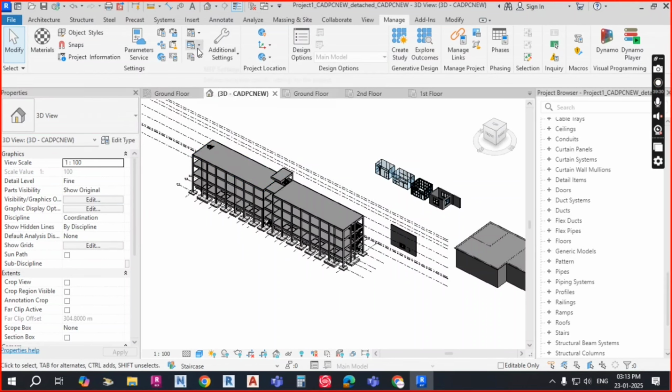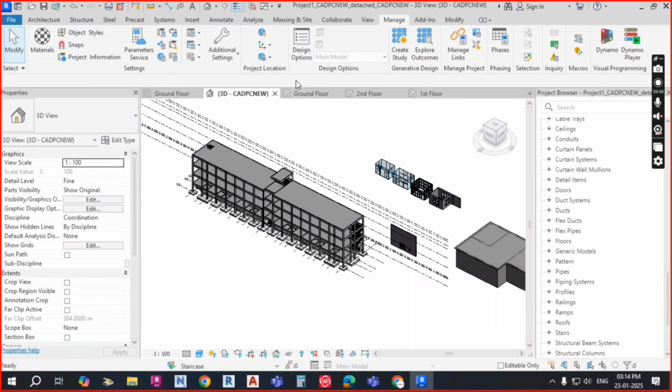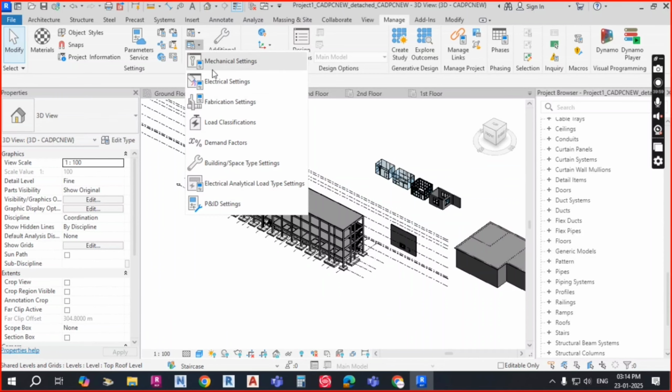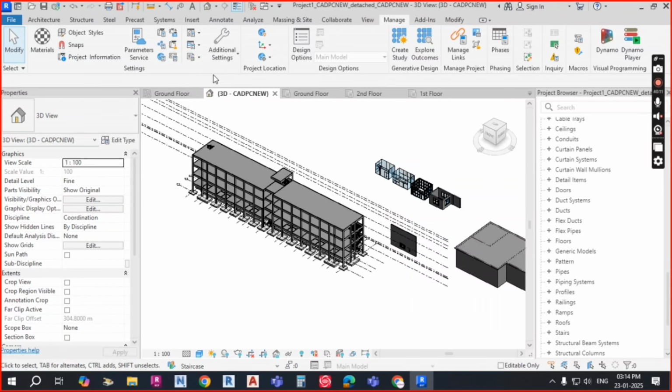Okay. So this is civil and this is MEP settings. So these are settings you can check once if required. And this is the electrical. This is civil, this is MEP, and this is separately electrical. Some panel schedule, panel settings, how we have to do. This is also very much important, because while working in electrical, how many cables, how many cable trays, and how many switches, everything you can give here by using these settings. Whatever settings you add here, it will continue for your project without any mistakes. It will become perfect as per the settings which we did in the project.